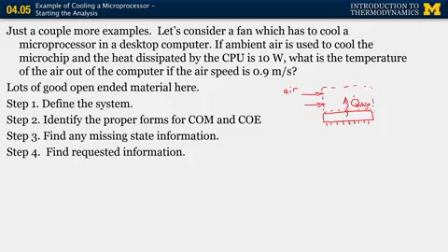But again, if you're asking for thermodynamic information, it has to be associated with the fluid that you're talking about. The system that you consider has to be associated with the fluid that is relevant for that thermodynamic data. So if you want to know the air temperature, the air really has to be the system you consider. So we've got this little box that's above the CPU, that's the air, where the airflow occurs in contact with the CPU.